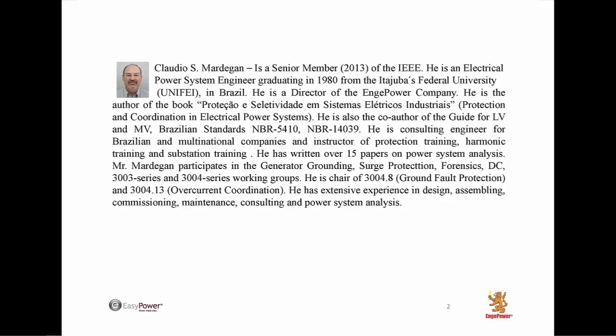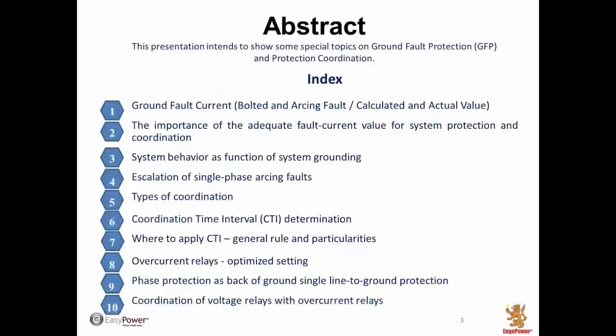Today we are going to talk about special topics on ground fault protection and protection coordination. We are going to divide our presentation in 10 topics: ground fault calculation, the importance of the correct calculation of the ground fault, system behavior as function of system grounding, escalation of single-phase arcing faults, types of coordination, coordination time interval determination, where to apply this coordination time interval, general rule and particularities, overcurrent relays, optimized settings, phase protection as backup of the single line to ground protection, coordination of voltage relays with overcurrent relays.